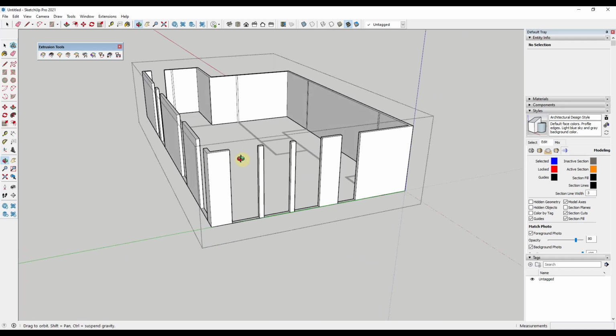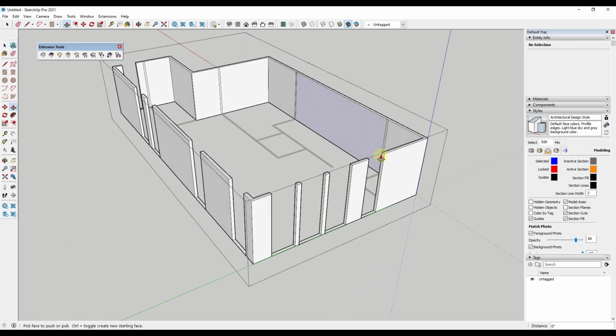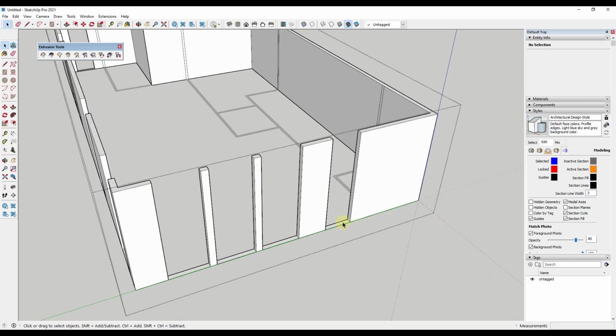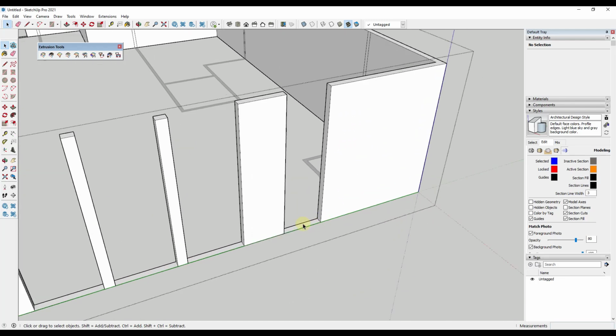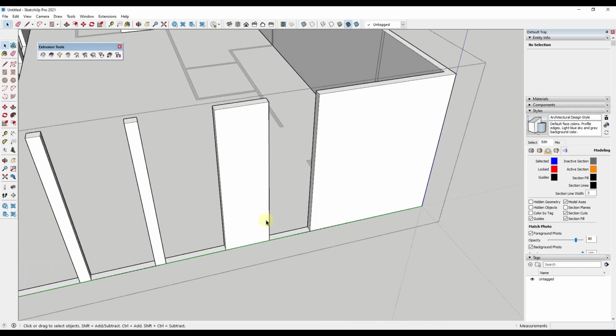And so what I've done here is I've basically roughed this out where I can see where my full height walls are and then my doors and windows. And then from there, we just need to rough out these openings for our doors and windows. And so a lot of the time, what I do in a case like this is I want to fill in this space above where my door would be. Well, I know that my door opening is going to have a height of 7 feet.